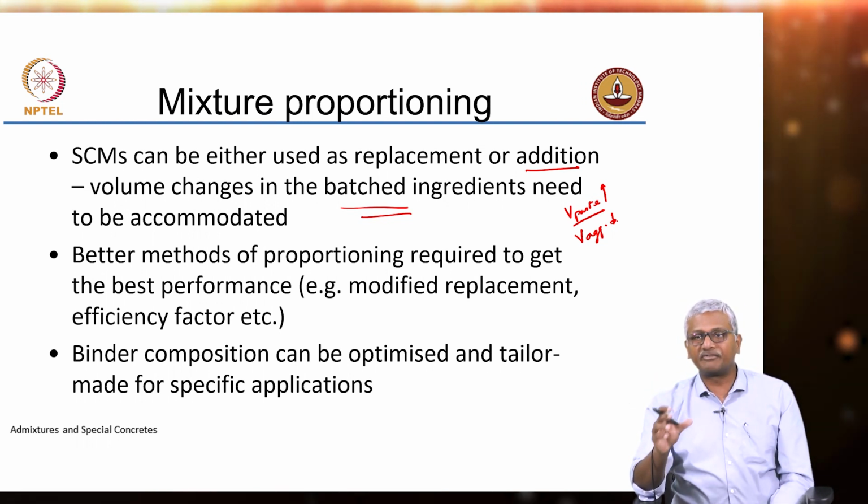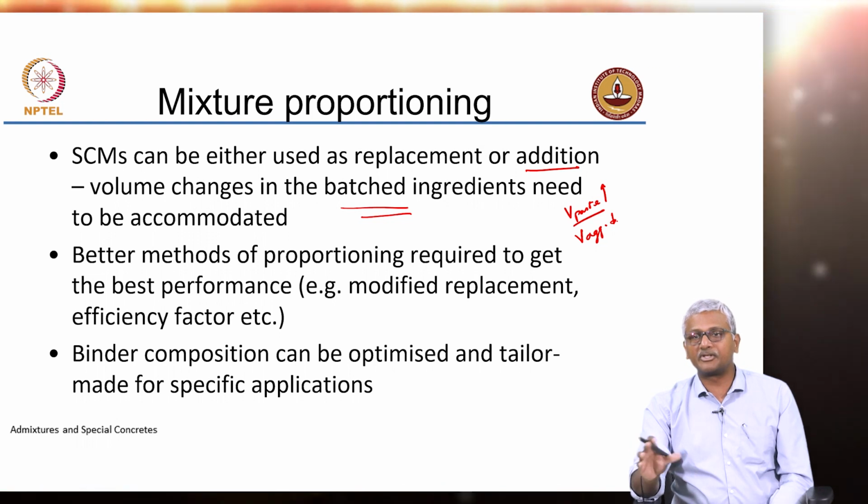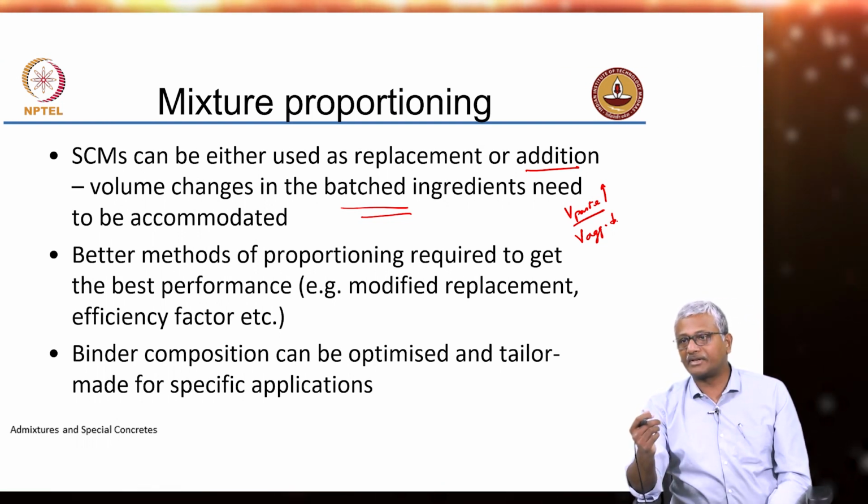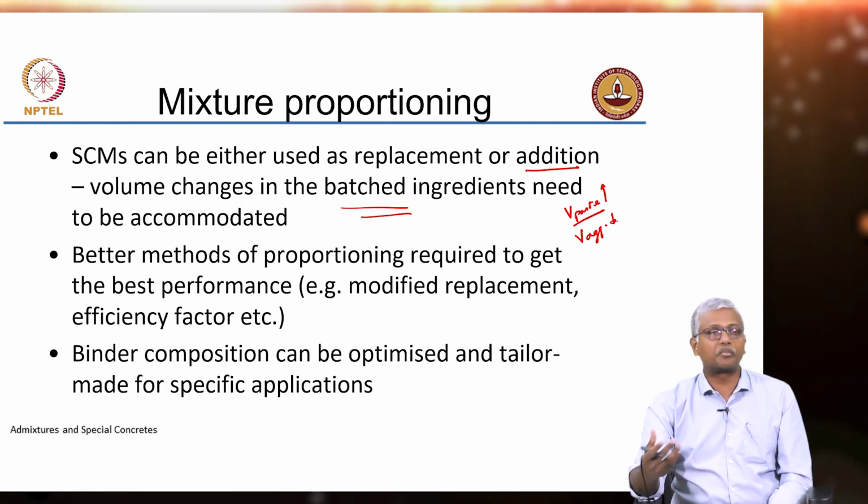Strength may or may not get affected, depending on the water cement ratio and how you design your mix, but shrinkage is going to be affected. Creep may be affected because you have more paste and less aggregate.